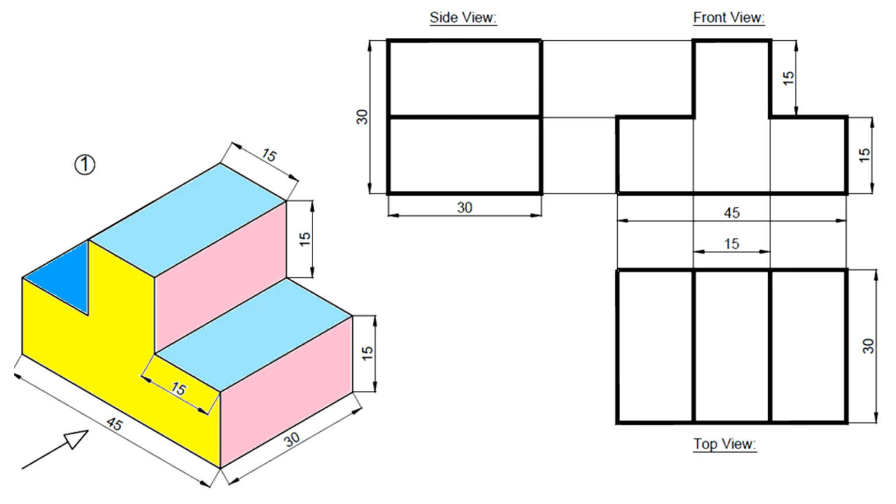And if you see the front view of this object, we need to imagine the object between the planes of projection. As the arrow mark is given here, the principal plane, the vertical plane, is parallel to this yellow color. So when you view this object from this side, you are able to see this yellow surface, and this yellow surface is a principal surface. So directly we can take the true dimensions of this surface, and then we draw the vertical plane.